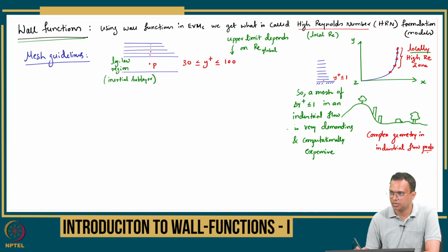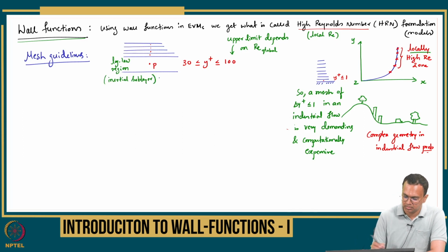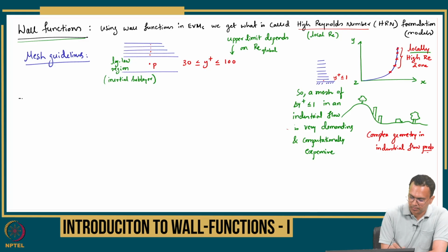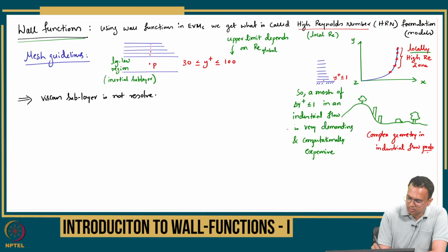So that means when you use wall functions, you are not resolving the viscous sublayer. So the viscous sublayer is not resolved. Resolved meaning you are computing, right? Resolved or captured in the CFD calculation. So what do you do then?